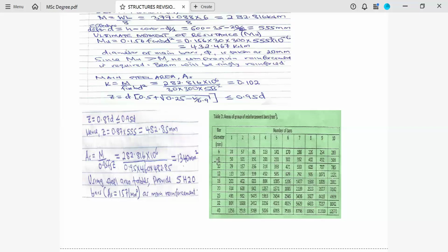You take any value here that is practical. But remember, in our country, Kenya, I think we cannot allow the use of main bar which is less than 12 millimeters. So you need to adopt at least a bar diameter for a beam of 12 millimeter going upward.